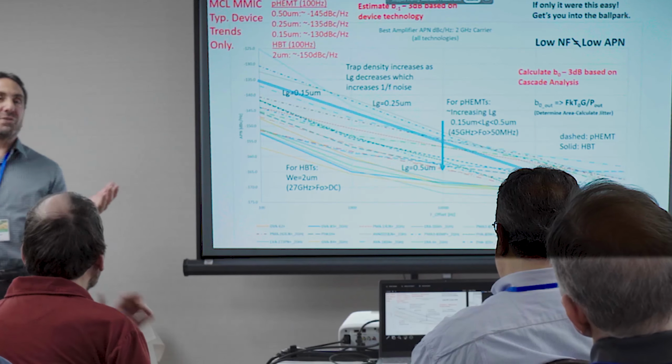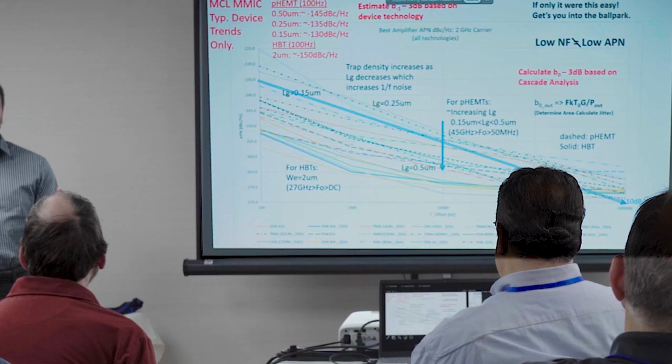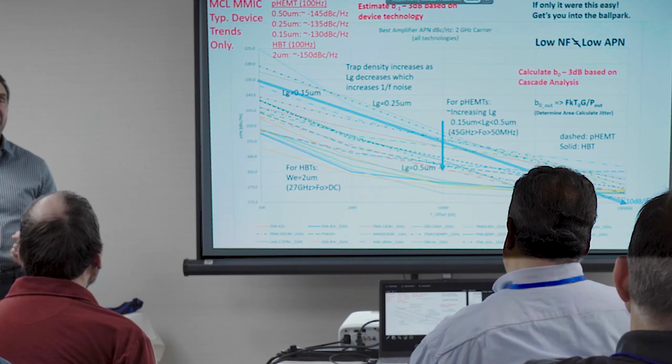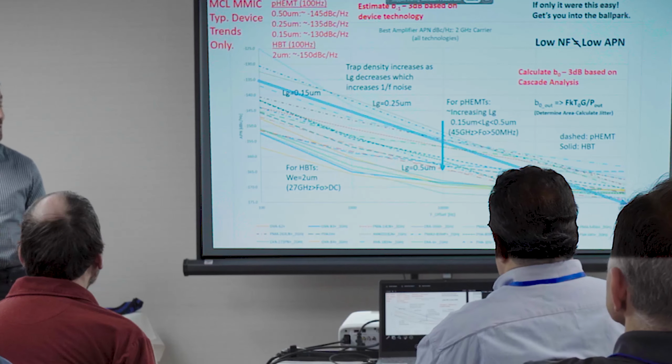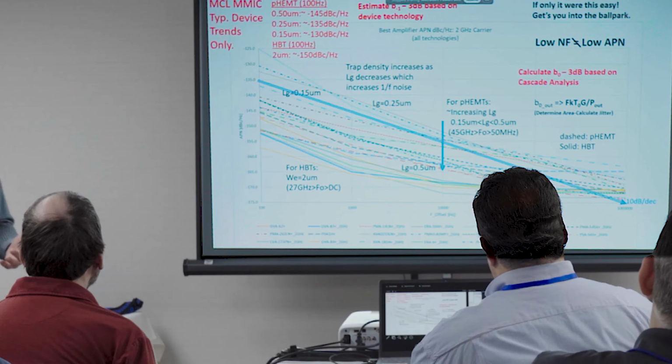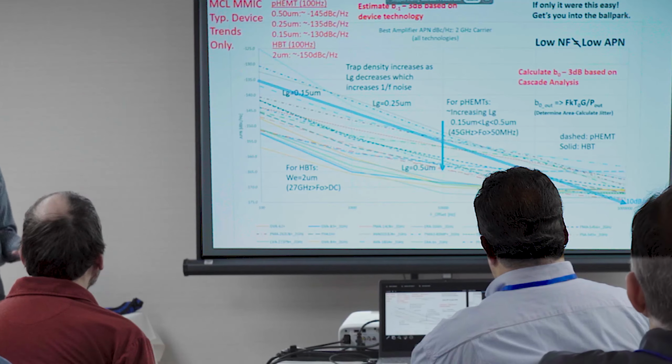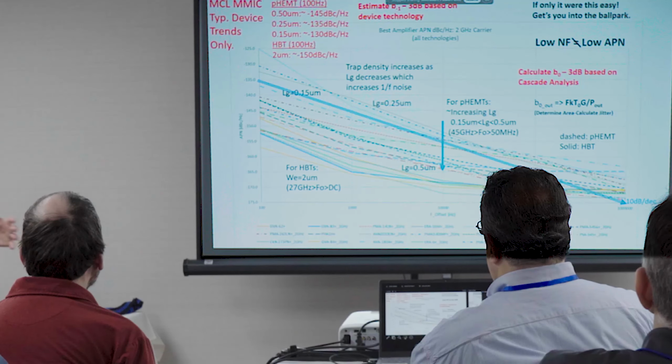So let me ask you, which is better? Is a PHEMT always better because it's got lower noise figure? Integrate the curves and find out. Does this matter to you? Do you care about 1K or less? Maybe you don't. I've had synthesizers where I just care about a megahertz.